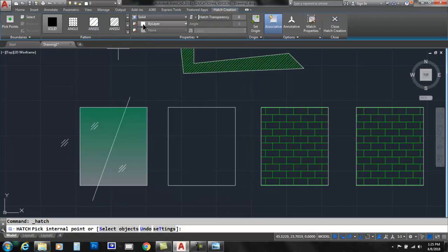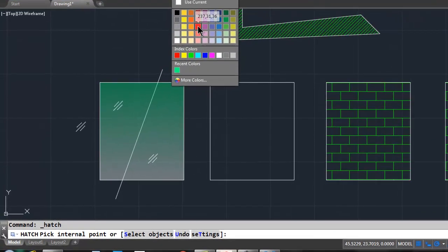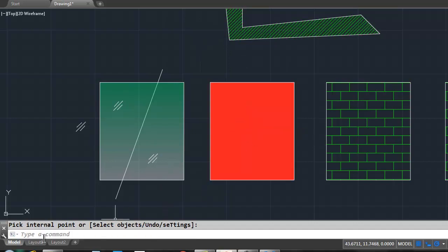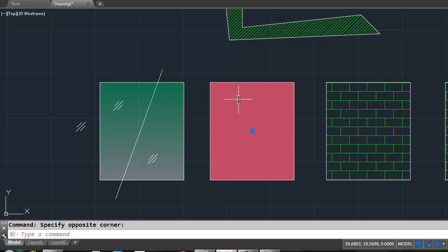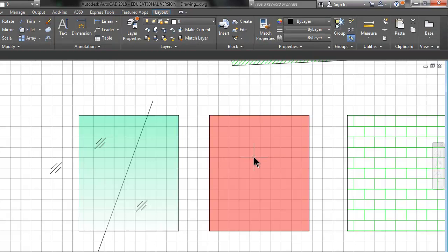I'm going to change my color. I can do this in one layer and change the color, and let's say I'll pick this real bright orange look. Okay, and then press enter. Now I'm going to go into layout and look at how prominent that is. So if I add some transparency to that, it'll tone that down. So let's say I'll go 50% transparent. Okay, and then I'll go back to layout and look at how toned down that is. Okay, so that's another tool at your disposal when you don't want something to be like a beacon of light in your drawing. Add transparency.